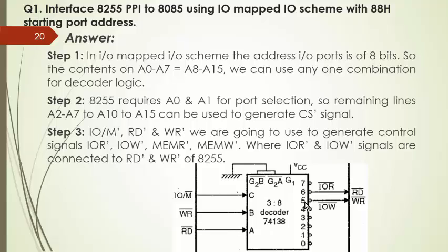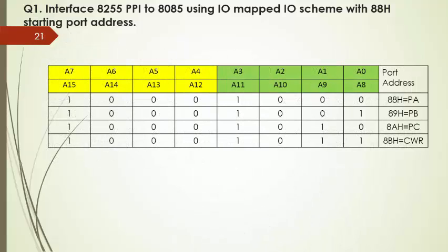As the bit pattern is 1, 0, 1, the fifth pin gets selected by the 3 to 8 decoder for the write operation. If an IO read operation is there, then at that time you get the bit pattern 1, 1 and 0. That is, the CBA pattern is 1, 1, 0, which means 6. So the 3 to 8 decoder will select the 6th pin. The 6th pin we use for the IO read operation, so the 6th pin we connect to read bar.